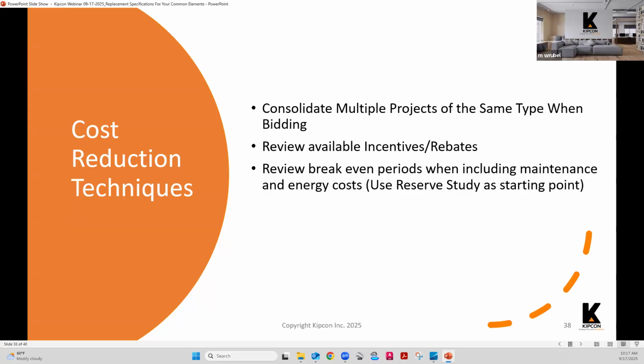And if you're doing something that's an upgrade, you may have an initial higher cost of replacement. And again, I use those examples of the wood and the segmental block retaining wall. Segmental block retaining wall to install is typically a higher cost than a wood tie retaining wall. However, it has a longer useful life, and the maintenance is virtually, I say virtually zero. There is some maintenance involved with it, but nowhere near the level that a wood tie retaining wall has. So you can look at the long-term cost savings of such a type of projects.